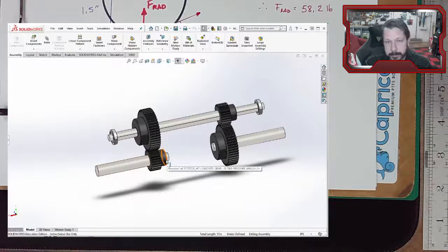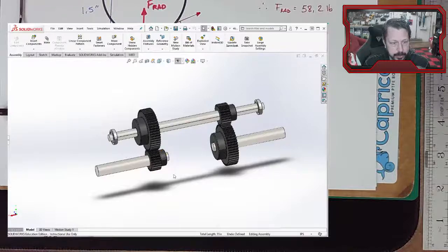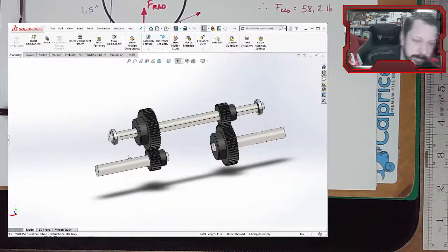The thing that can happen with a short shaft is that maybe it doesn't deflect, but it just shears, like it just breaks off. Normally you ignore that transverse shear component because there's way more happening stress and deflection wise. But on a really short shaft, stress and deflection aren't that big a deal because it's short, and what starts to dominate is the direct shear. You just have to check that also. That's the very last mention in chapter 7.5: being sure to check for direct shear of the shaft. It just breaks through shear.